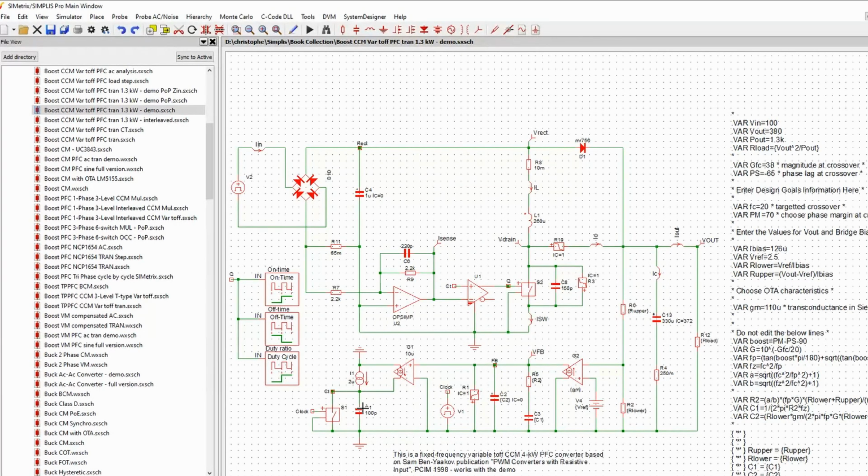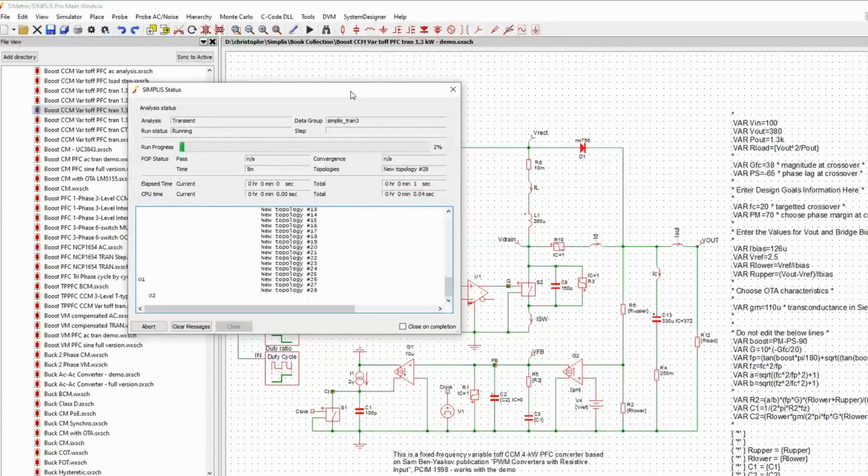If you simulate this type of circuit, at least if you would like to have a few mains cycles, so maybe 400 or 600 milliseconds, it will take ages before it actually delivers the results. And also the granularity, if you want to look at the various switching transitions, it's going to be hard to obtain something meaningful. Here, what is very cool is that I can put an AC source here, and if I press this guy here, you will see immediately how fast it simulates.